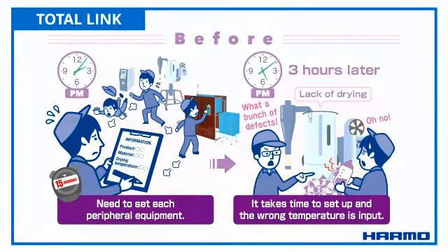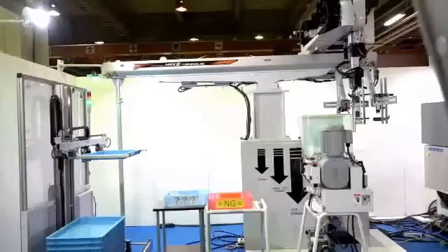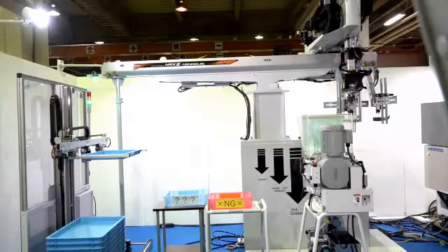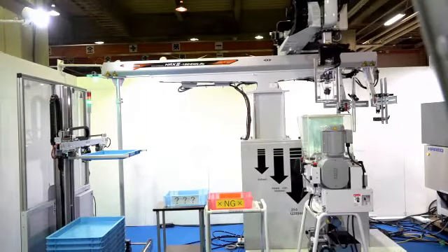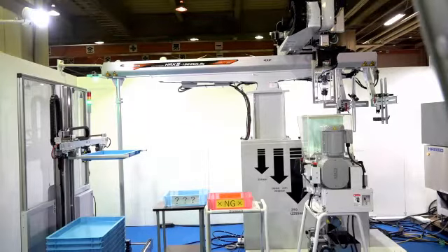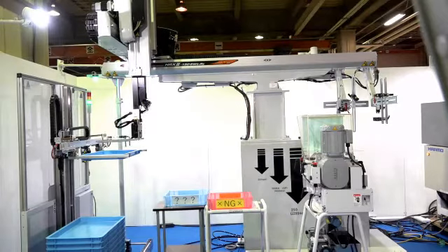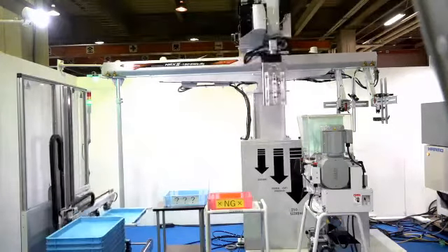Let's solve this problem next. The defects are found because the operator doesn't notice the slight changes of the equipment. We have the robot communicating with the dryer and mold temperature controller. Let's see how it is working now. Okay, so take out the gate with the wire nipper one more time, and then release the runner to the grinder cutter, and then go to the box filling system. This is normal operation for this robot. Let's see one more time.